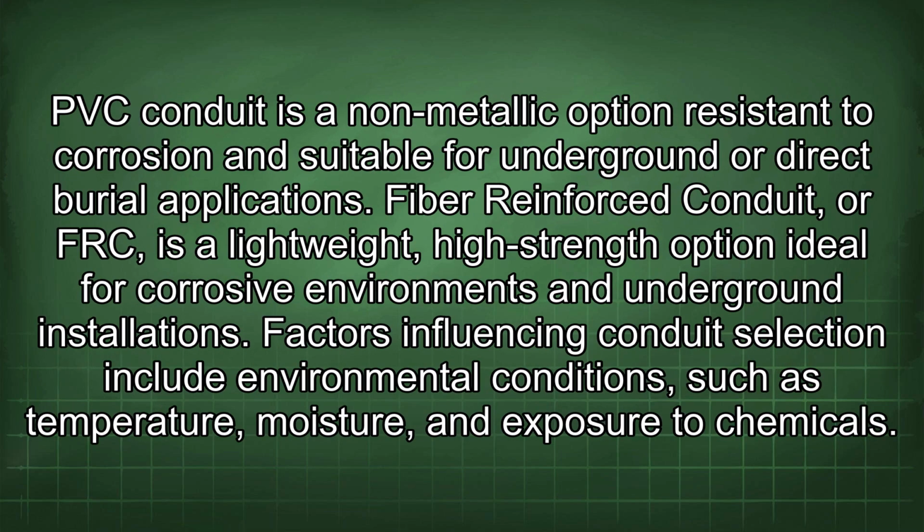PVC conduit is a non-metallic option resistant to corrosion and suitable for underground or direct burial applications. Fiber-reinforced conduit, or FRC, is a lightweight, high-strength option ideal for corrosive environments and underground installations. Factors influencing conduit selection include environmental conditions such as temperature, moisture, and exposure to chemicals.